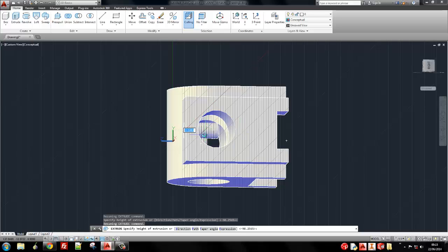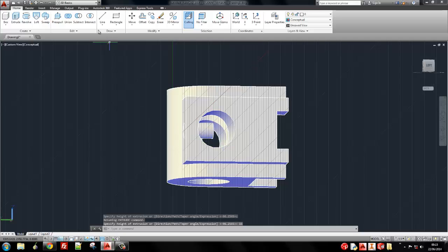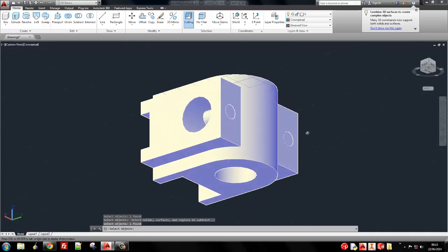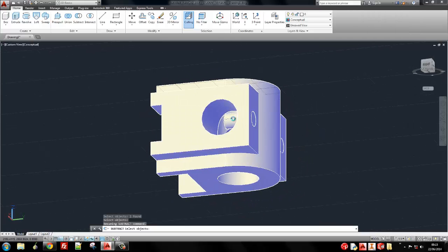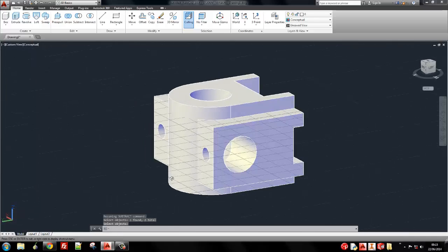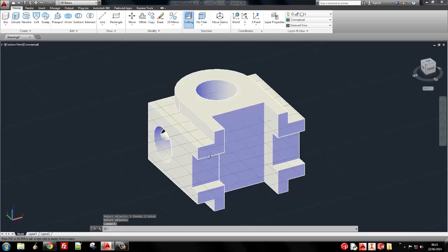It doesn't matter how deep the extrude is, as long as it's going through the top face of this outer profile and not through the bottom face of that circle. So around about there, 18 would be fine. I'm just going to type in 15 just to make sure I don't go over the top. There we are. And again, we're going to extract that material by using the subtract command. Subtract the big object and my two littler objects. There we go. Ta-da! Okay, and that's it complete.